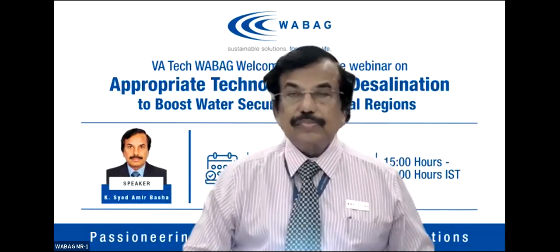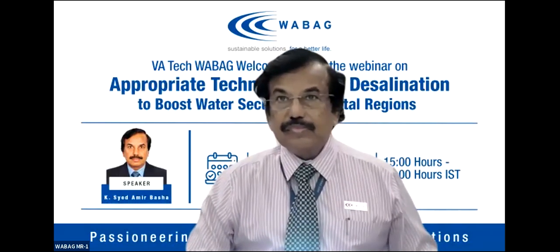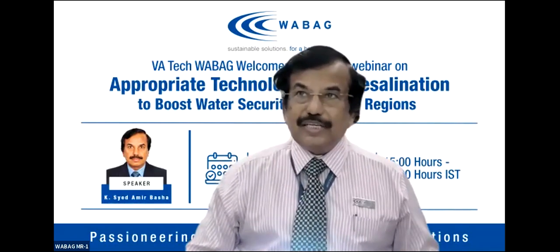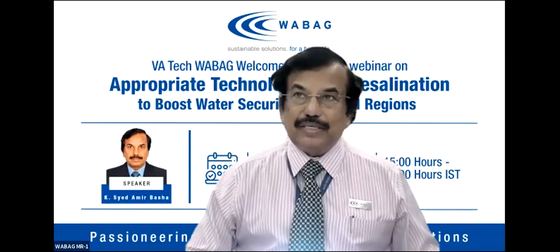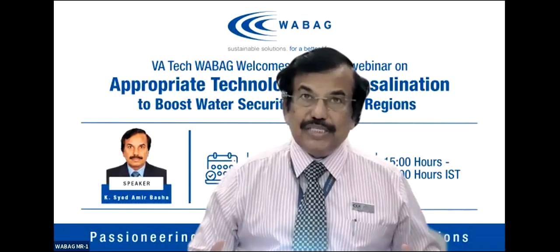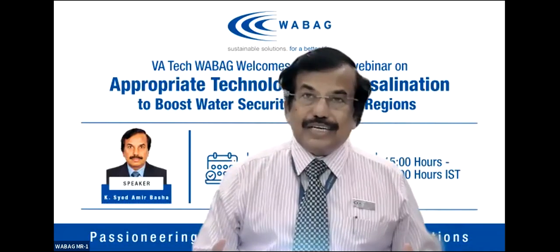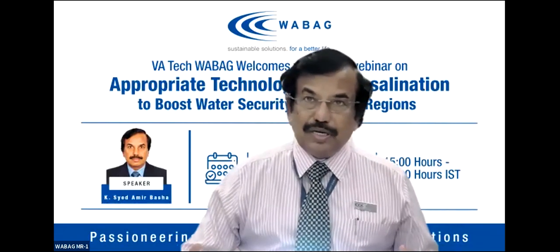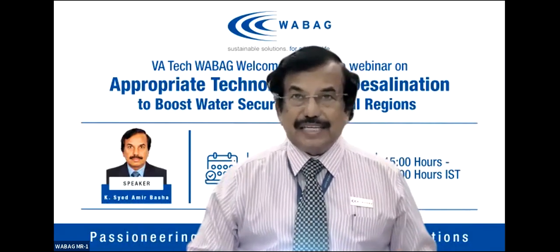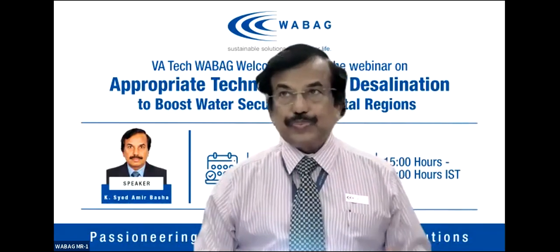Thank you, Mr. Amir. The next question is from Mr. Sultan Ahmed. In which plant are the lamellar clarifiers used? The plant which I am operating, the 110 MLD Nemmeli desalination plant, uses a lamella clarifier. We operated even during the cyclone, with a TSS of around 1,490 milligrams per liter, and we got a lamella clarifier outlet with 20 milligrams per liter of TSS, and the plant operated during the entire cyclone.